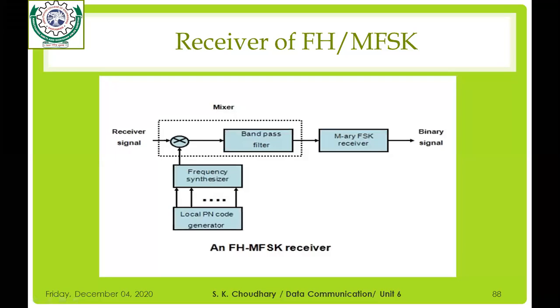Okay, so here the received signal is applied to a mixer, and the other input comes from the output of the frequency synthesizer. The output of the multiplier has two components: the sum of the received signal frequency and the frequency synthesizer frequency, and their difference. So both sum and difference signals are generated at the multiplier output.